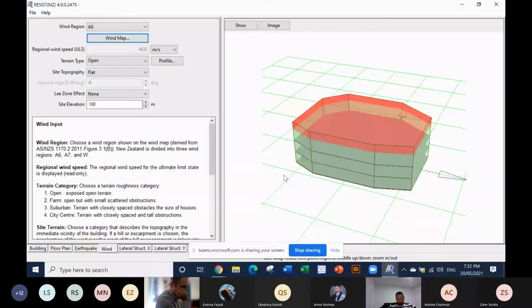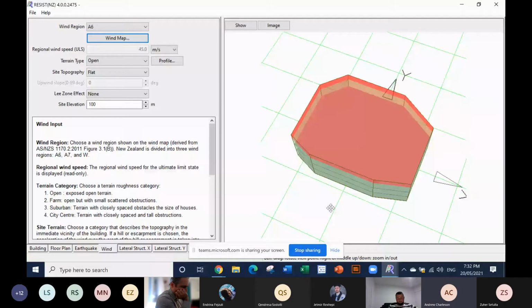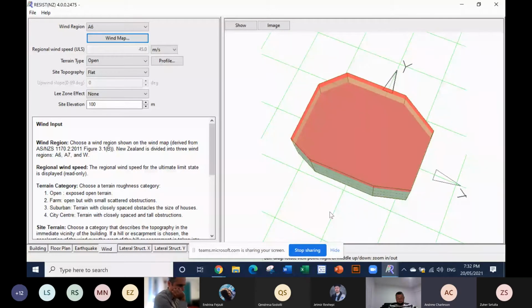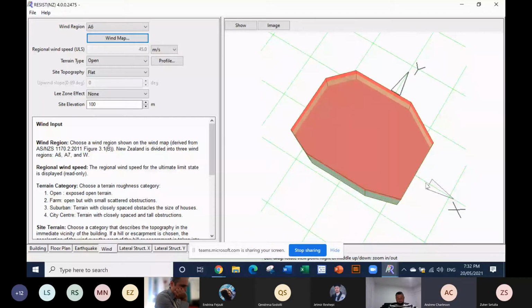Now you'll see the building plan is sort of related to 2 axes. There's the x-axis and the y-axis. And so the first principle in earthquake-resistant design is that every building we design must have resistance in both the x and the y directions. We must always provide this resistance in both directions on both of these axes. So let's design the structure to resist earthquake loads in the x direction. We'll do that first.